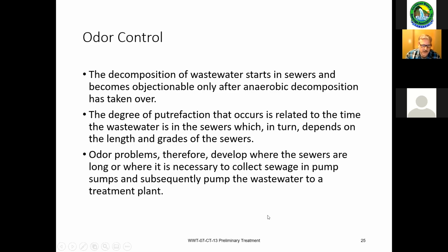One big thing about odor control too is if you can have bylaws in your system or oversee construction in your city or municipality to reduce or eliminate long-standing lines of sewage in pipes. Our bylaw, for example, states anything in a force main cannot sit there for longer than 45 minutes. So we try to keep everything moving, rather than having development farther out sit in the line and go septic, which causes odor concerns throughout your system, but is also very detrimental to your treatment facility.